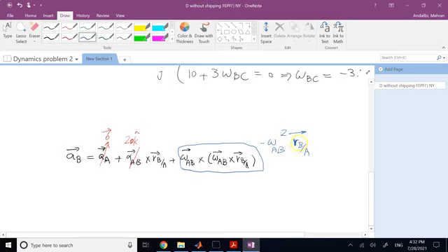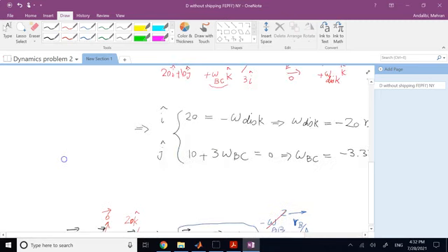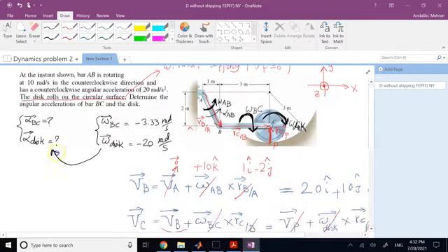This simple formula that I have here is a scalar, because this is just a scalar omega AB squared, it's a magnitude. This scalar times the vector, instead of carrying out two cross products, is only valid when the problem is 2D like this, or when you have cases like R and omega are 3D but they are perpendicular to each other, then you might have the chance. But in general, you cannot always go from here to here. In this case we can, so let's carry that one, makes life easier. So this magnitude omega is simply the number that we had, which is 10.